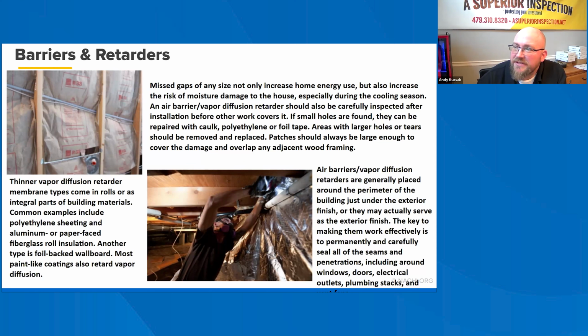In mild climates, materials such as painted wallboard and plaster wall coatings may be enough to impede moisture diffusion. In more extreme climates, higher perm vapor diffusion retarders are advisable for new construction. They perform best when installed closest to the warm side of a structural assembly, toward the interior of the building in cold climates and the exterior in hot, wet climates.